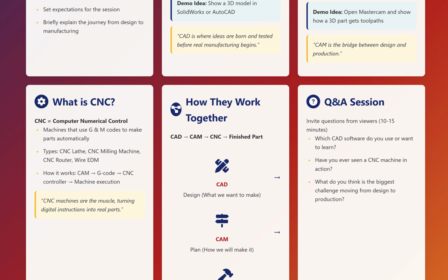Some of these machines are the CNC lathe, CNC milling, CNC router, and wire EDM. It normally works in simple ways. You have to design your product. From this design, you give a CAD output in terms of a soft copy. The soft copy CAD models are put into the CAM. The CAM software translates the CAD models into G-codes, which you generate for a CNC. The CNC controller then automates the execution of the G-codes.